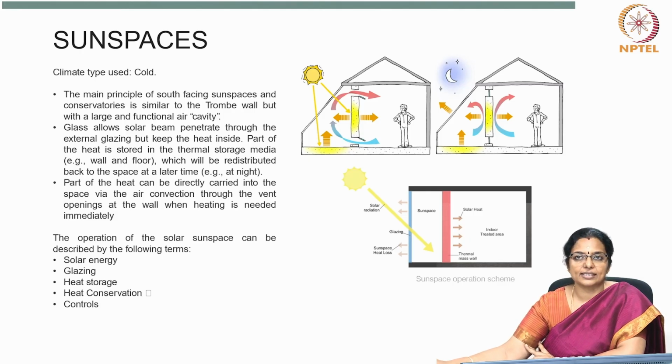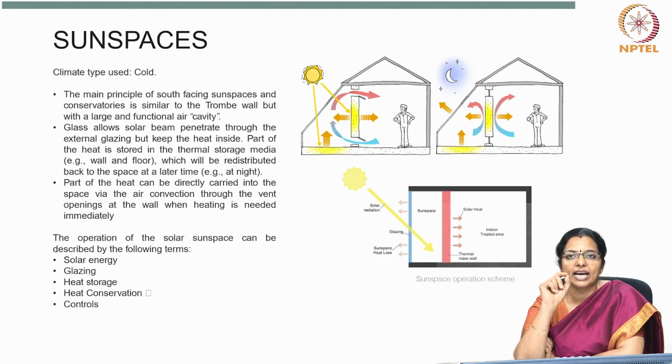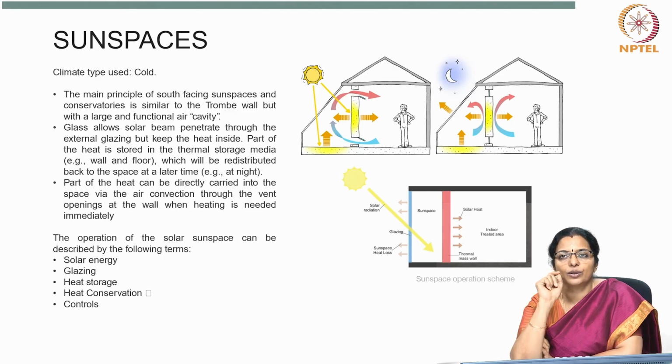the angle of incidence. Multiple glazing could also be used, and the use of more than one layer helps in reducing the heat losses, as the gap between the layers, which is usually air, acts like insulation. But the transmittance is connected to the absorptance and the reflectance of the glazing. By raising the glazing layers, the transmittance gets lowered. Thus, even if the heat losses reduce, at the same time, the heat gains also are negatively affected.